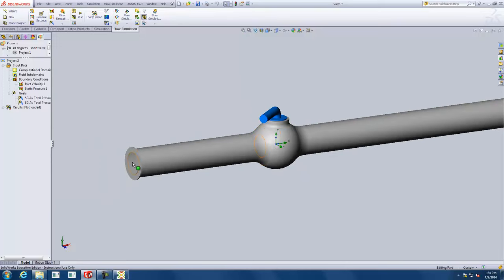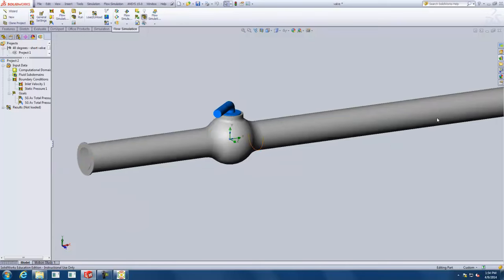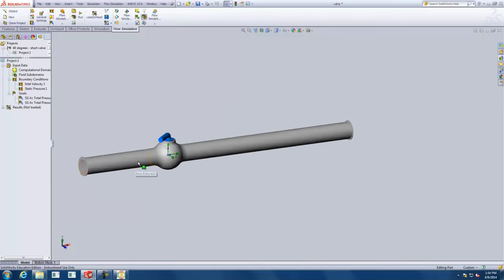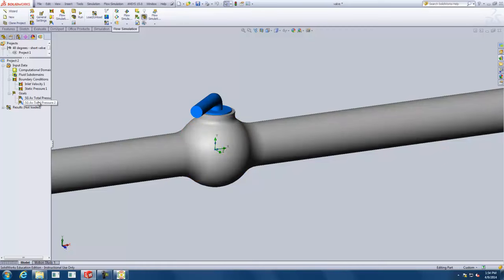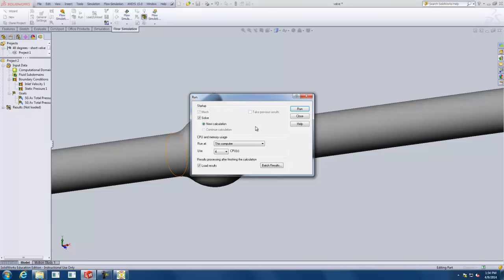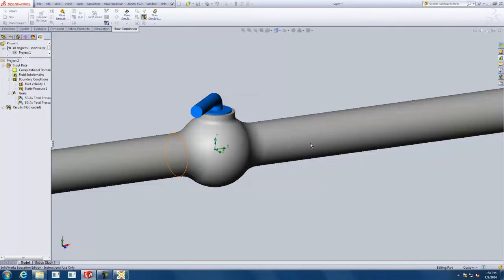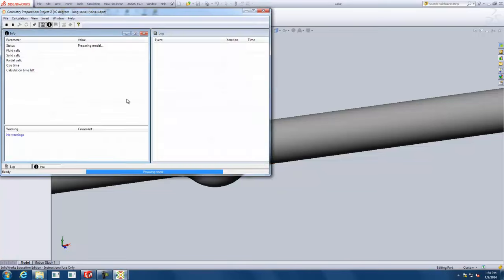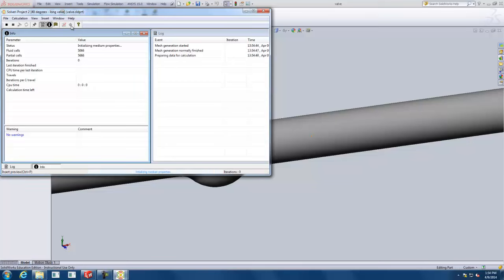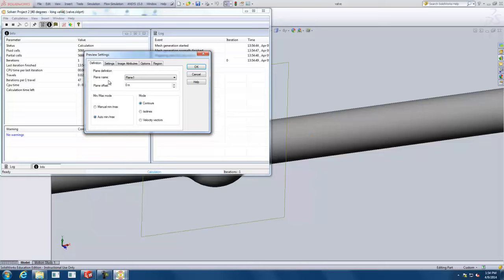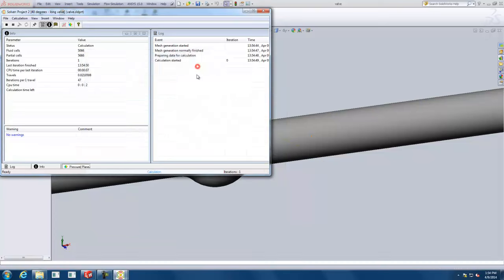All right, so you can see here now the lid's still out here at the end, and the lid's still over here. We still have our boundary conditions defined. We still have the total pressures defined. So we're ready just to go ahead and run with this new model. Again, it's a new calculation. Everything else is set up the same. And this time that it's running, we're going to watch for this guy to become colored, and then we can use that to actually preview what's happening. So we'll click on that, and we'll go to, you have to figure out which plane it is, but plane 2 is going to work well here.